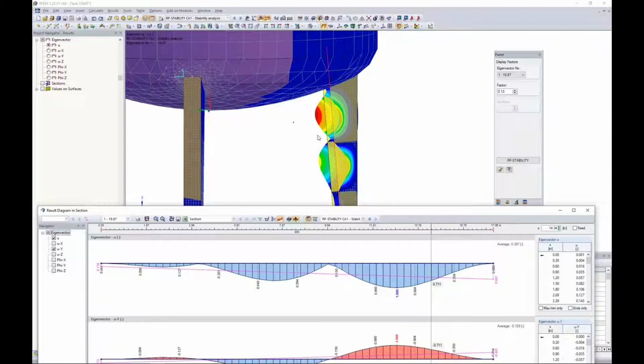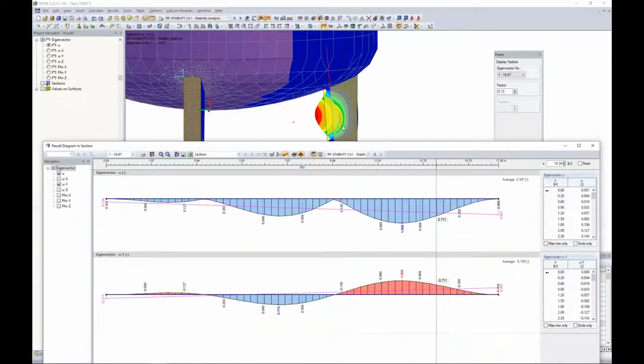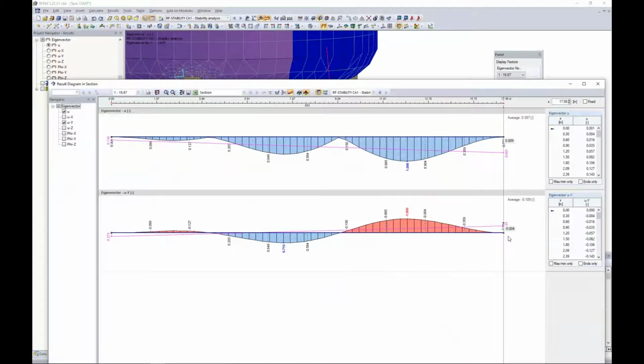This comes from the AISC Code of Standard Practice, and in particular, Section 7.13.1. It discusses misalignment of members and surfaces. These tolerances can be less than L/500, where L is the distance between working points. Keep in mind that L is not the distance between the start of my surface and the end of my surface, but rather I want to use my working points where I see my inflection points. So looking at the general buckling view here, I take a look at the first inflection point taking place at about 10 inches, and then I scroll over here to the end at 17 inches. Well, this would be my working point at about 7 inches in total.